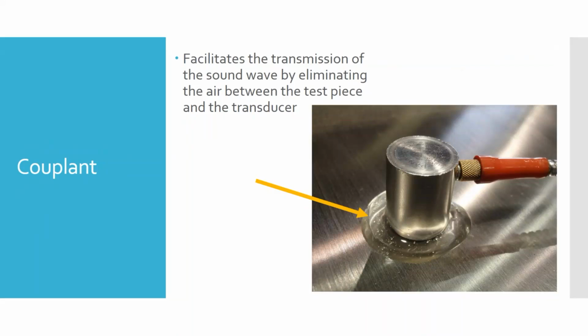Here's the little one. You'll use these probably more than any. So between the face of the transducer and the workpiece, we'll put this, and that's going to fill in and bond. It's going to fill in all those little air gaps and everything else, and bond it. And that's going to help transfer the sound into and out of the material as smoothly as possible.